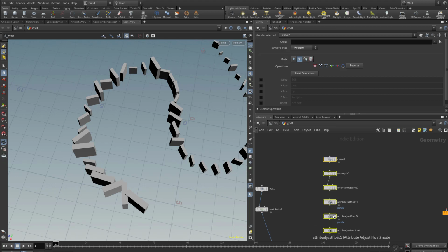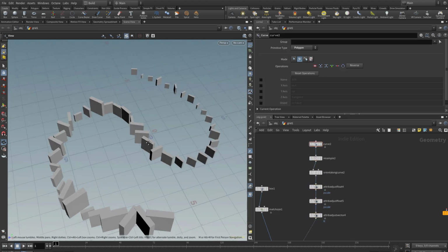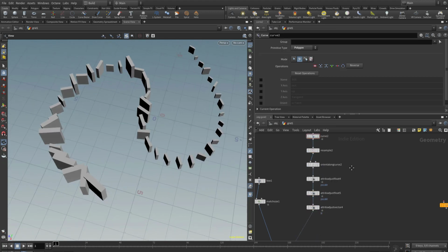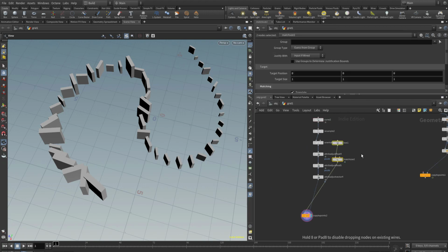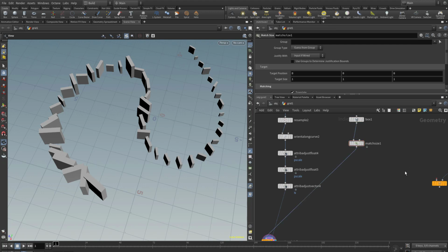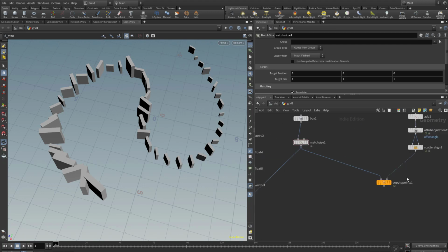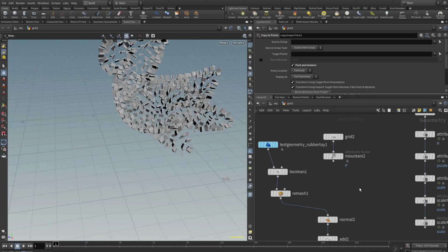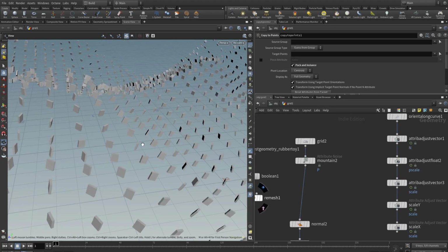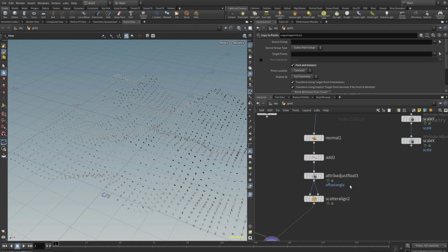Now as a final thing, and that will apply to this as well, how can you do non-uniform scale? The default non-uniform scale attribute is called scale. So pscale is uniform scale and scale is non-uniform. Scale is a vector. So let's do one thing. Let's take this over here to this guy. Let's take the grid back over here. Okay, this is good.